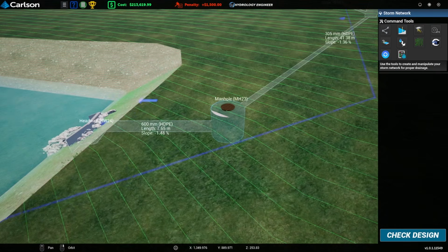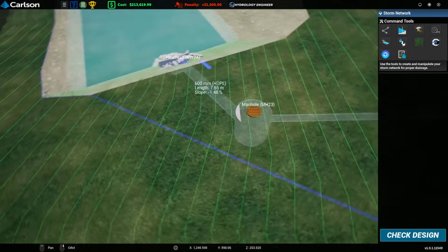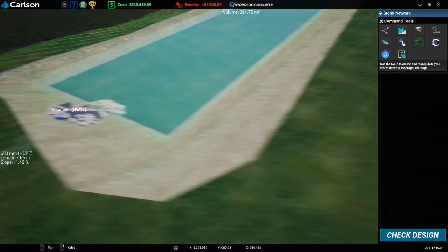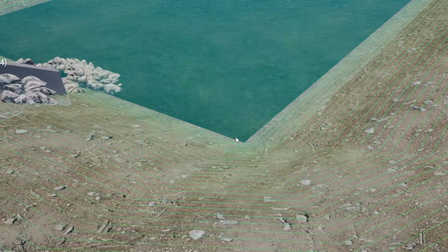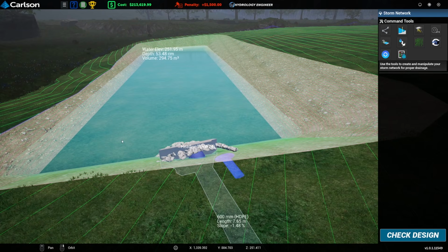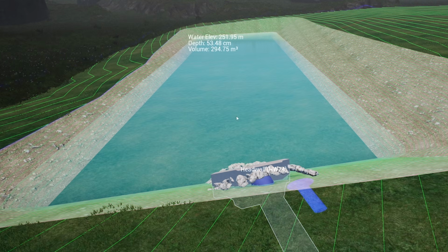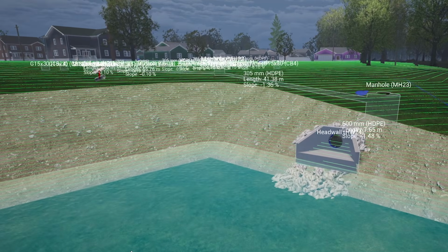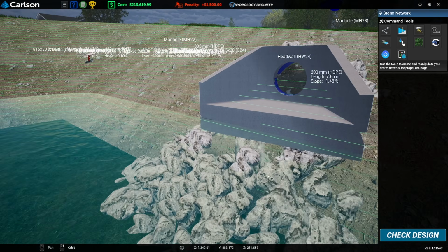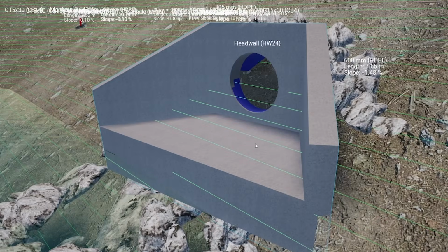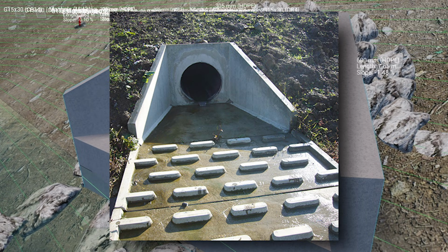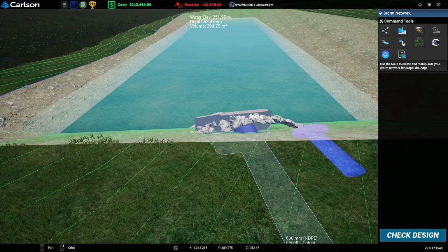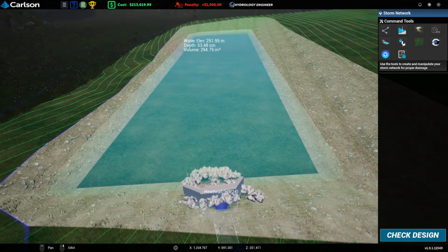All right, so you might be wondering, well, Matt, why did you put a manhole there? It's so I could angle this head wall so that rather than the water entering this place at a corner, it enters on this edge, so it has this nice long length of pond, because the water as it comes out there is probably going to be going reasonably fast, because this is quite a lot lower than up where those houses are. And whilst we try and limit the flow velocity, like we've got rocks here, you may sometimes see we put little concrete blocks on this sort of surface to slow the water down as well.